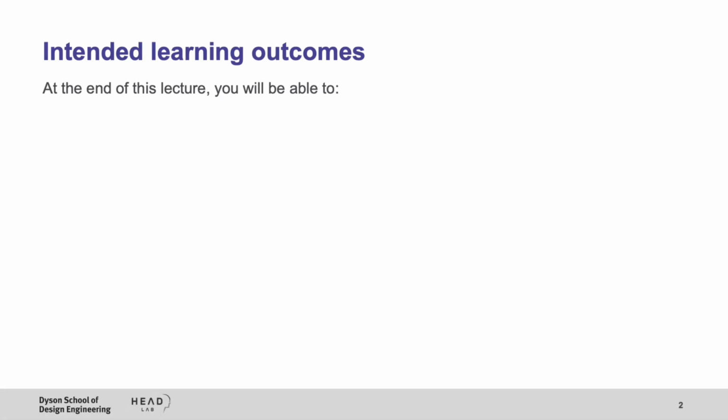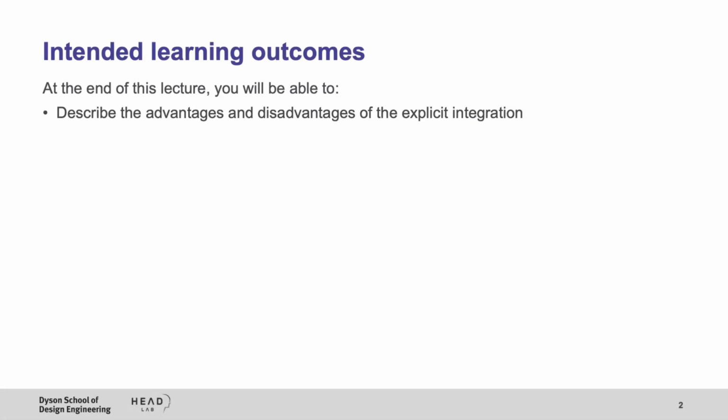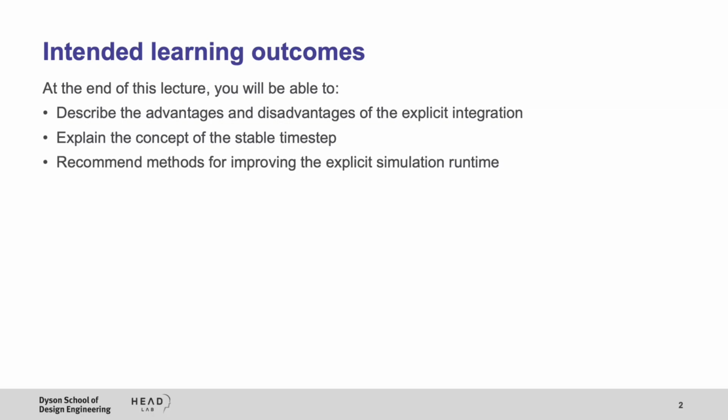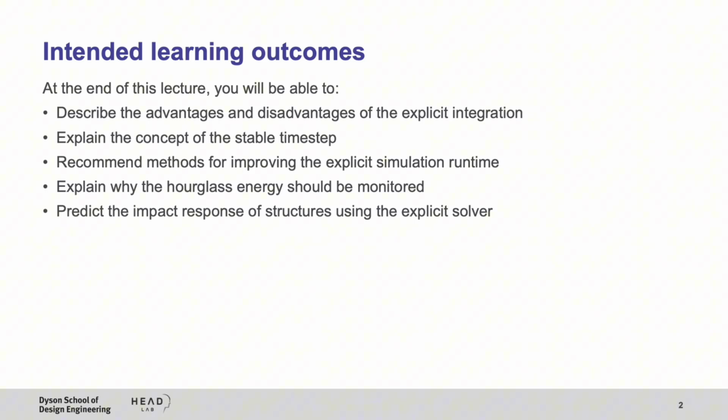By the end of this lecture, you will be able to describe the advantages and disadvantages of the explicit integration, explain the concept of the stable time step, recommend methods for improving the explicit simulation runtime, explain why the hourglass energy should be monitored, and predict the impact response of structures using the explicit solver.